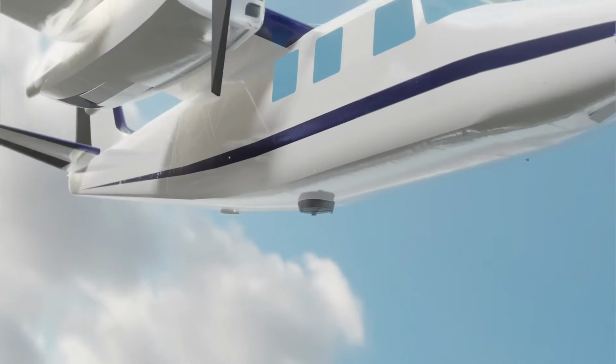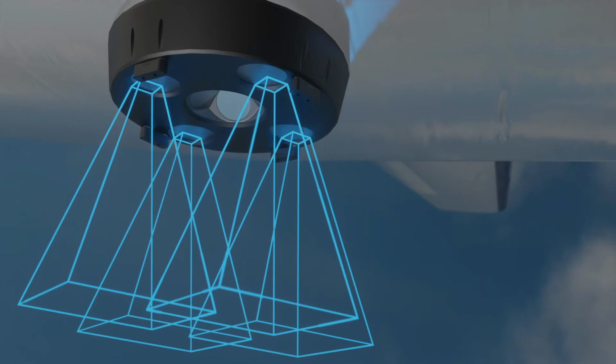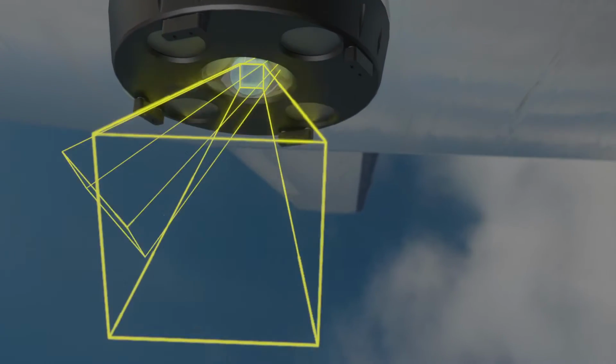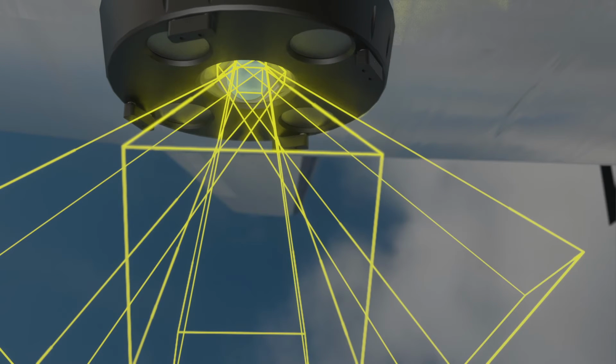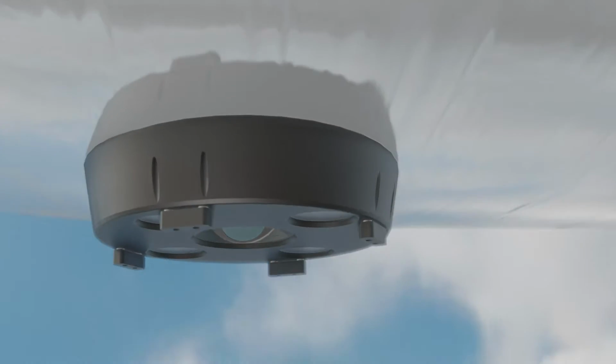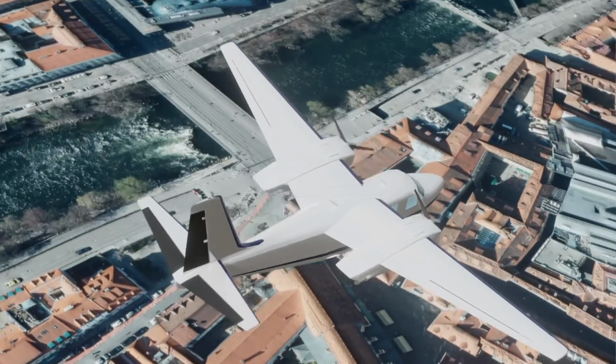So in the UltraCam Osprey 4.1, the nadir looking cones for the pan channel, for the near infrared, for the RGB are oriented at the outer ring of the camera system, and the oblique cones are in the inner part of the camera, looking crosswise, left and right and back and forward. With this setup we are overall achieving an optimized field of view, and that limits the potential obstruction with structures of the airplane to a minimum and eases the installation and allows the camera to be installed in a wider range of planes.